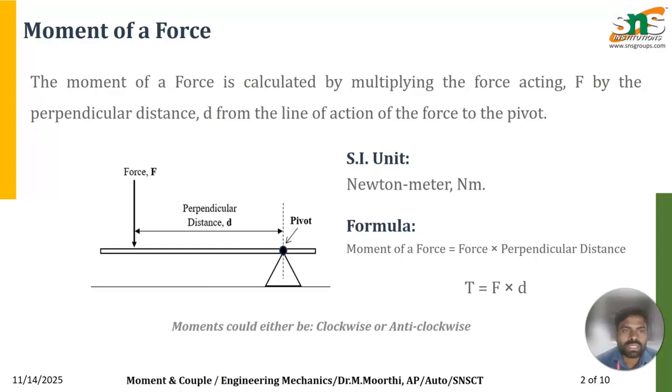Here, the moment of a force, as I said earlier, is the rotation produced by a single force acting at some distance from the reference point. The moment of a force is calculated by multiplying the force by the perpendicular distance from the reference point. So the moment is equal to force times distance. The direction of the moment depends on where the force is applied with respect to the reference point. The moment is either clockwise or anti-clockwise, and the unit of moment is Newton meter.